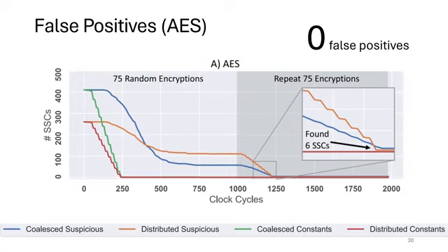But the answer to that question I asked is here. Those 32-bit and 128-bit registers that take a long time to cycle through those values, instead of going through all the millions of clock cycles necessary to eliminate those, the team just repeats the same encryptions, which means they repeat a value. And so those are also eliminated without having to go through every single possible value that they can hold.